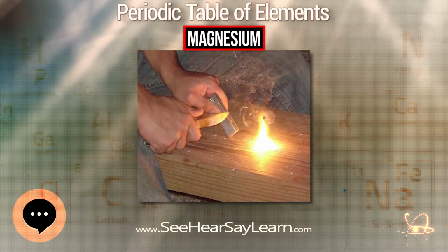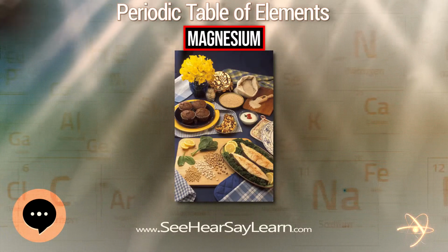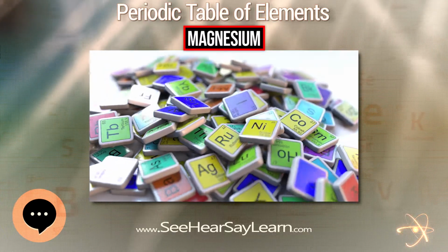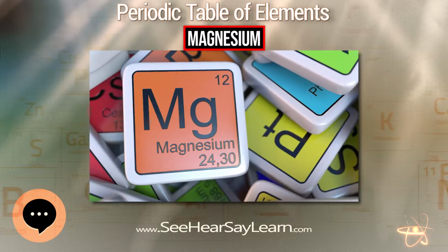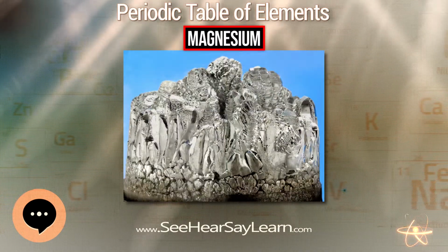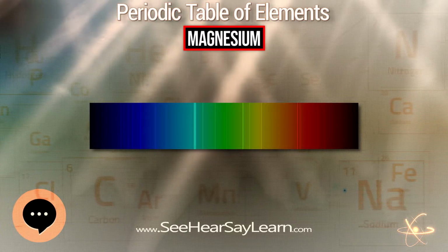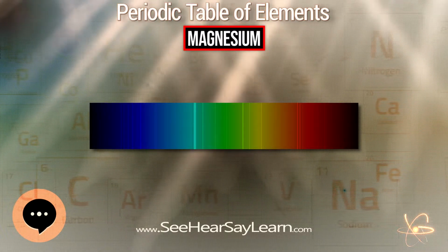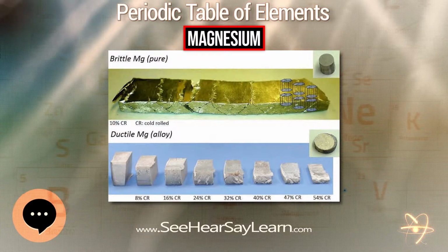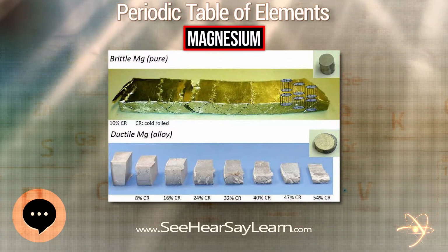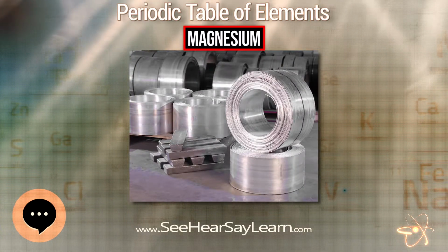of nearly 10. Research showed that magnesium's tendency to creep at high temperatures is eliminated by the addition of scandium and gadolinium. Flammability is greatly reduced by a small amount of calcium in the alloy. Magnesium forms a variety of compounds important to industry and biology, including magnesium carbonate, magnesium chloride, magnesium citrate, magnesium hydroxide, magnesium oxide, magnesium sulfate, and magnesium sulfate heptahydrate.